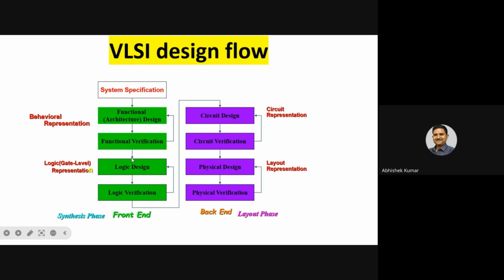In logic design, because I told you we have billions of transistors, billions of logic gates, we cannot do the manual task, so we go for programming. With programming, every program we are going to convert into gate level representation. That I'm going to discuss under logic design. This conversion is called synthesis. Okay, that is what I've written here, the synthesis phase. It is the process of translating Verilog code or a Verilog program into the gate level netlist representation.